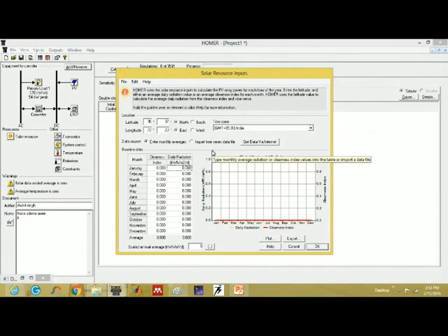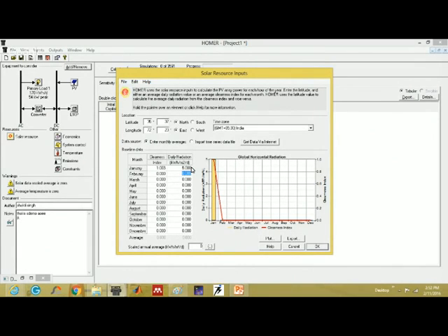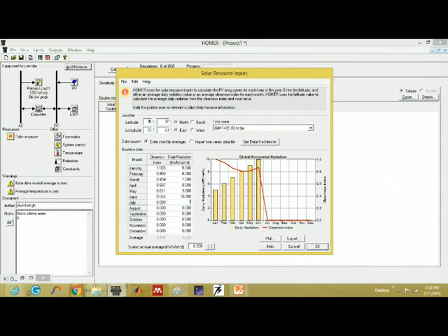You have a Word file and you want to import your data, and let's say in January I have 5 kilowatt-hours per square meter per day average solar radiation at my site. In February, let's say again 6, in March it goes on increasing, 8, 9, 10, like July also 10, August a little down, September again down, October 7, then 5 and 4, let's say. So this is site-specific data. This is the clearness index. Clearness index is how sunny the day is, right? How clear the day is.